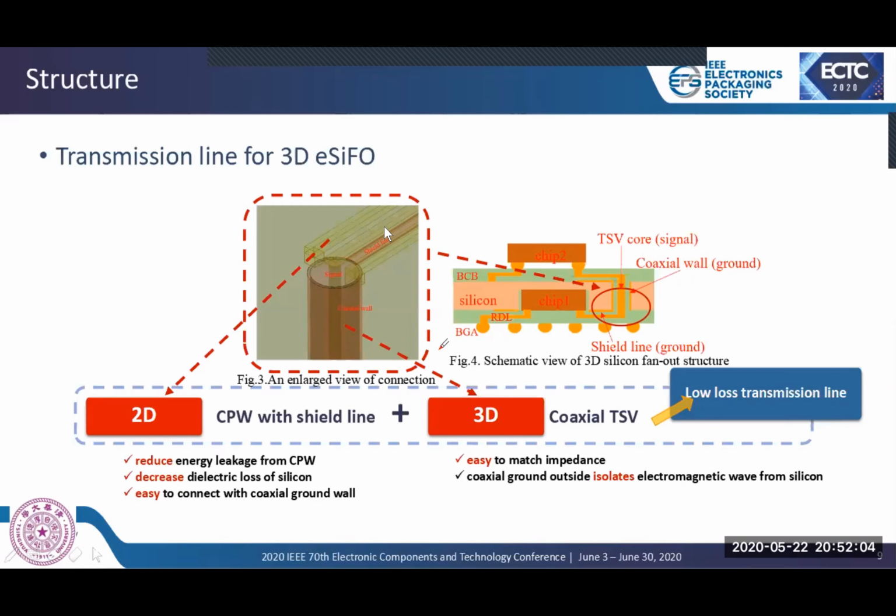In addition, the green part of Figure 4 is BCB. It is filled in the coaxial through silicon via and coated on both sides of the silicon substrate due to its low-loss property. BCB is also the polymer for redistribution layer fabrication and filled in the small gap between the chip and between the die and the side wall of the cavity on silicon for the convenience of process.